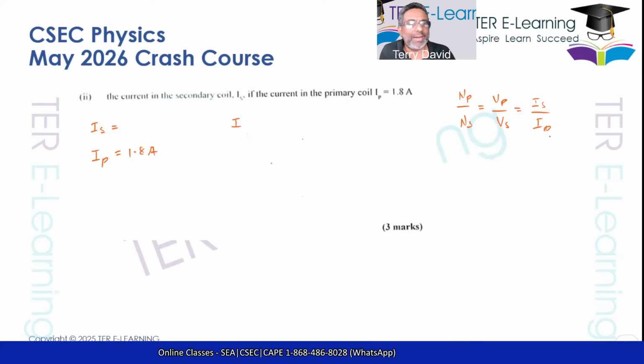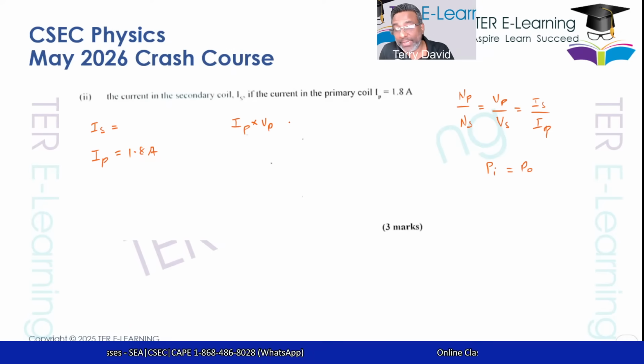Now, personally, I've never liked this equation, even when I was in Form 5. I still don't. So what I do when it comes to current and voltages, I see it in terms of power input and power output. So your primary current by your primary voltage, that's your primary input power, is equal to the output power, which is the secondary current multiplied by the secondary voltage.